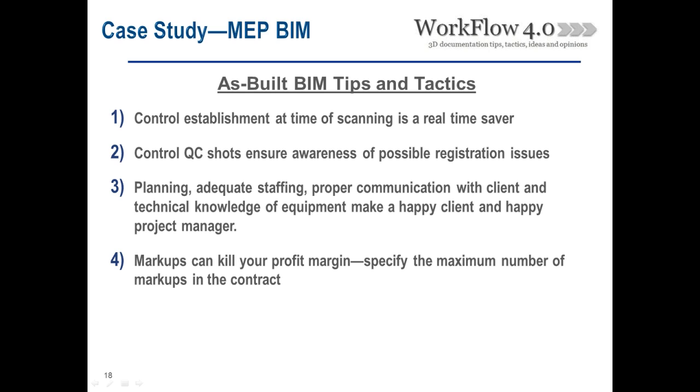As far as the as-built and BIM tips and tactics, control establishment at the time of the scanning is a real time saver, and it allows you to kind of keep everything independent. Once you're on one site, everything's done. The control has been laid, the scans have been collected, and you can pretty much pull all your targets down at that point in time. It saves a lot of time for one, keeps the sanctity of your targets good at that point.